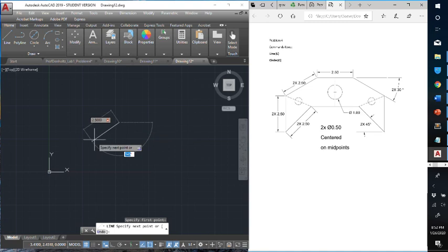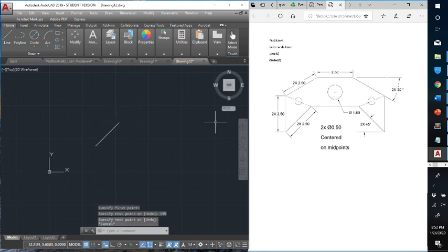So this is a little bit of a mathematical question, or a trigonometric question. I could say that it looks about 45 degrees here, right? Well, that's correct. It should actually be 135 degrees over here. And so 135, enter, and we have that value in. And the next one, we're going to come up by 2.5, but let me go back to the angle. So here, this is 45 degrees. And so we know that if we were to come down to the left from this line and then go straight out to the right, that this corner would be 45 degrees. But here, they want it to measure from here to here.